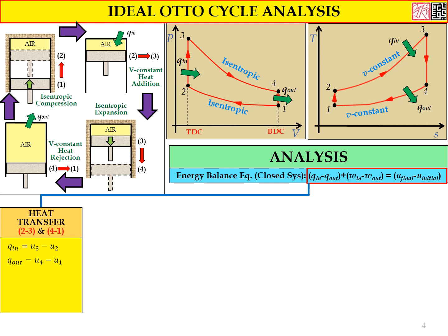At the same time, we don't have any Q in, only the Q out parameter. So the remaining terms in the energy balance equation are only Q out and delta U. That's why we have Q out equal to U4 minus U1.